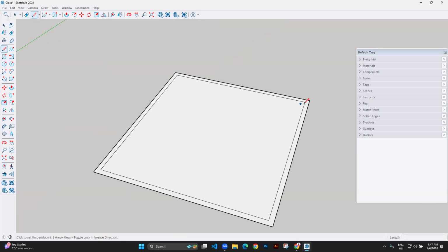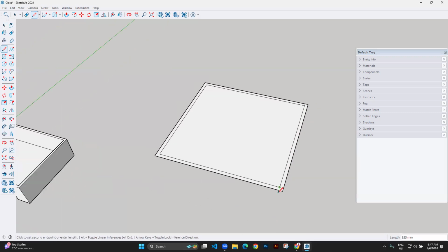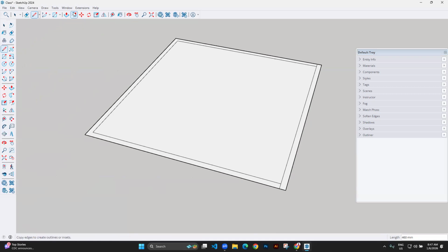I get line and I complete one of them, so that I'm going to create more faces. If I do that, now I can push pull this face. See, this is still joined, so let's right click it. That push pull. Now I have this, this, this, and this.